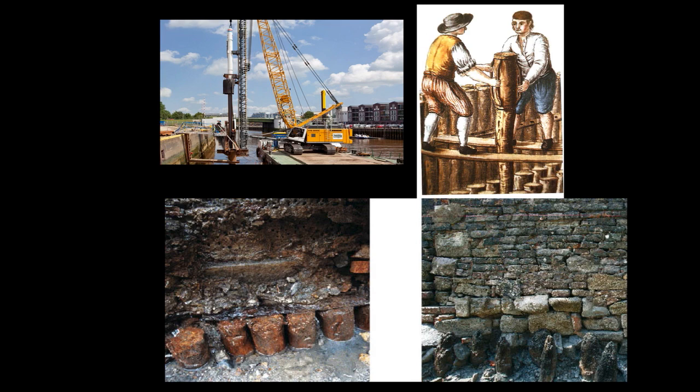Well, you do it with what are called pilings. And these pilings, basically the technology that they had available to them at the time, were basically logs with pointed ends that were pounded into the mud. Now, in wet locations, in coastal locations, we still sink pilings into the mud.